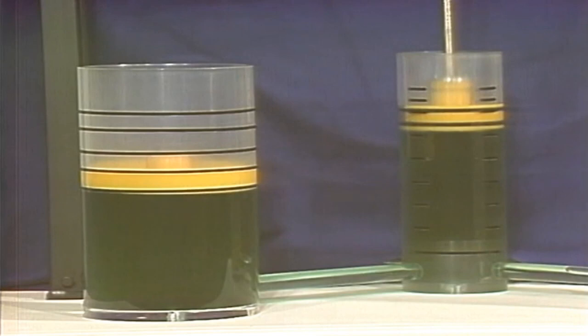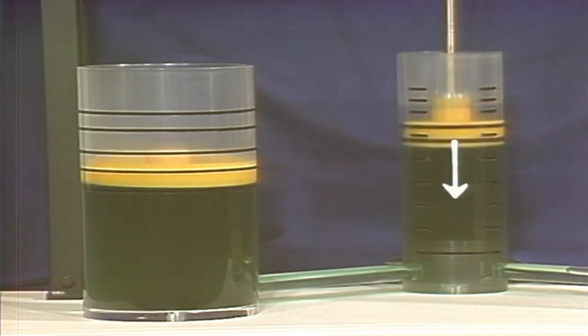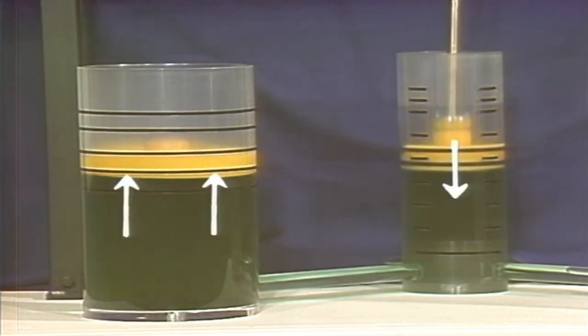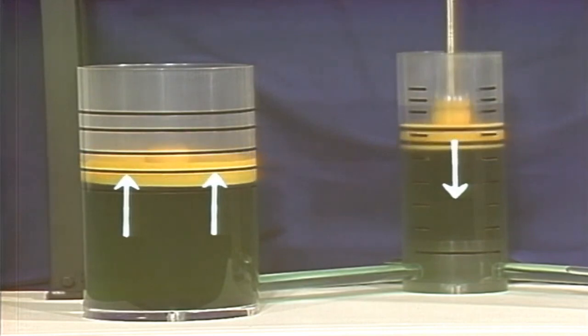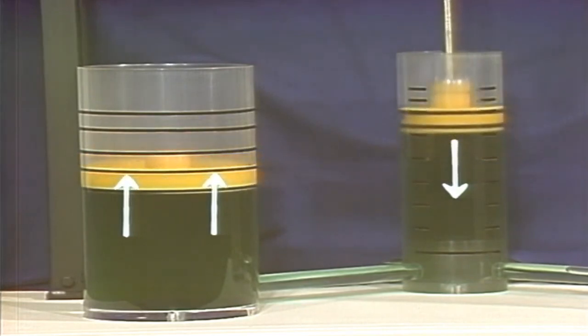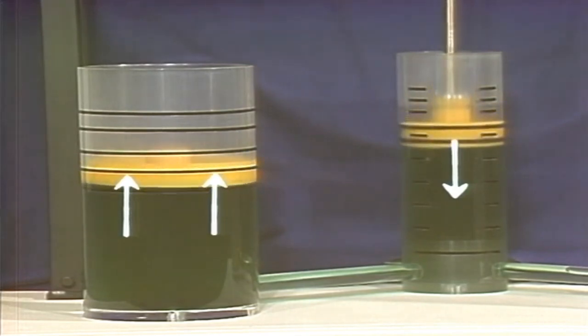Let's see what happens if one piston is bigger than the other. The small piston puts a certain amount of force on the liquid. At the larger piston, the same force acts on each area that's the same size as the small piston. So the pressure on the face of the large piston is multiplied by that amount. This means the force applied by one piston can be multiplied many times just by enlarging the area of other pistons in the system. One other thing happens. The smaller piston has to travel farther to raise the larger piston by the same amount as before.